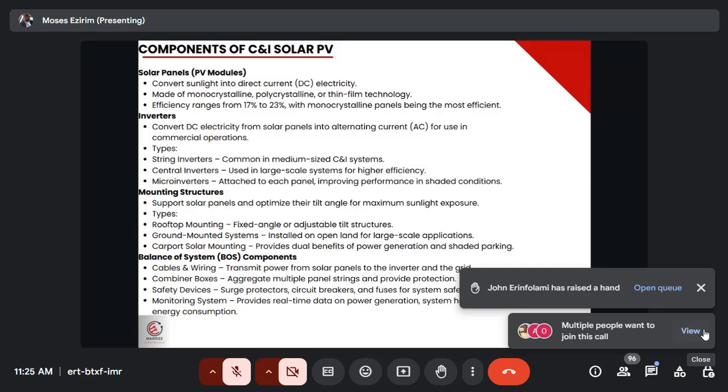You understand? The reason why you need to do that is because you need to meet up with that monthly energy. But if you are not monitoring it and you've done your installation, you won't realize that 2 inverters, 3 inverters, 4 inverters are not yielding. It is not just installing and you allow it to go. There might be some issues. You understand?